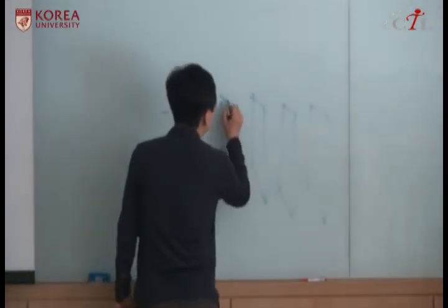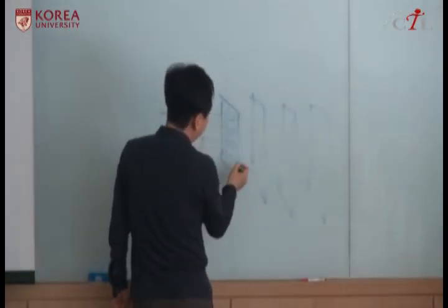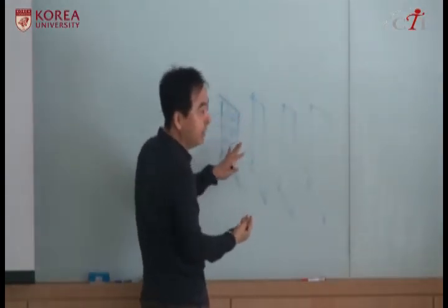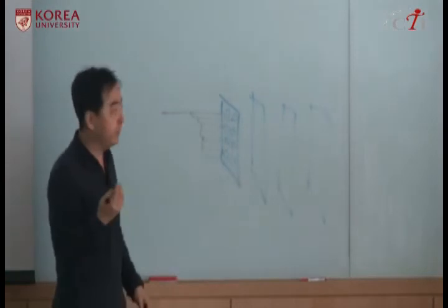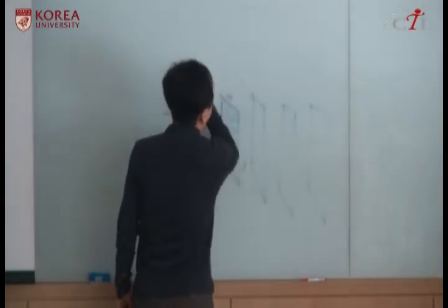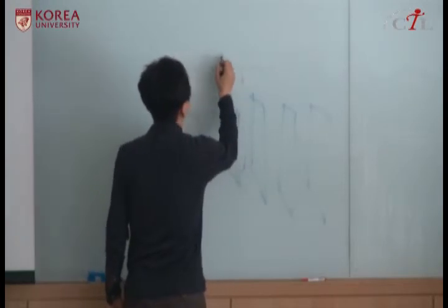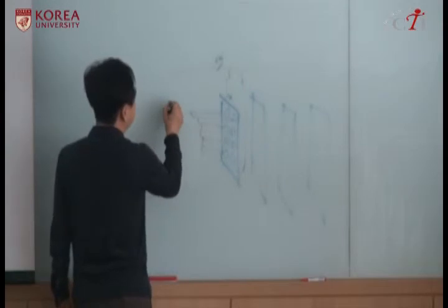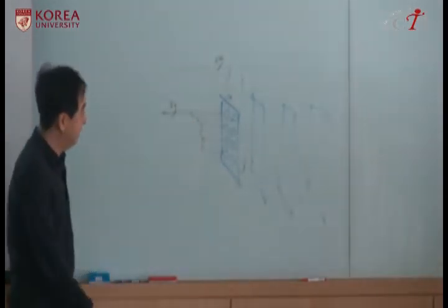Data lines are actually every bit they work in parallel. So you have 8 chips here, 8 chips on the back. So 16 chips, each chip produces 4 bits. So 4 bits wide, 16 chips, they become 64-bit data bus. So 64-bit data bus and maybe let's say 32-bit address line coming here.